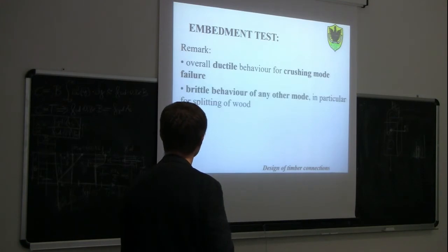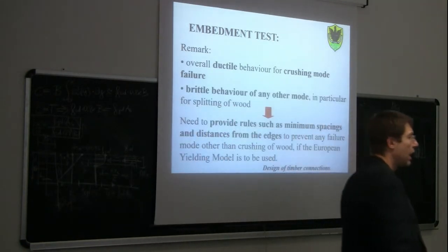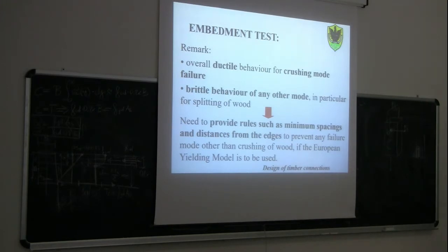So, now, how can we ensure that the failure modes, which are brittle, will not occur in our connection? As I said before, we need to make sure that those failure modes will not occur, because otherwise we are not able to use this equation, this Johansen equation.